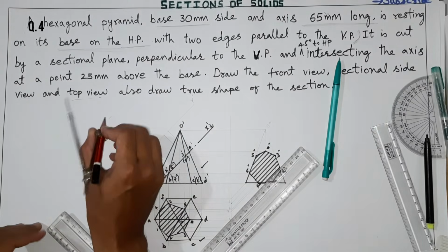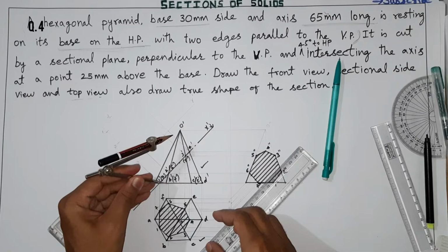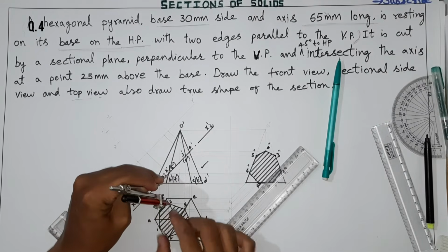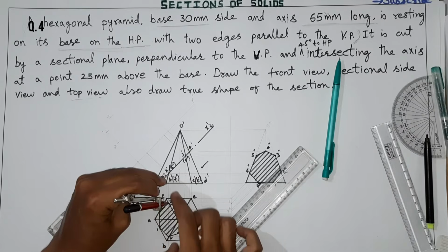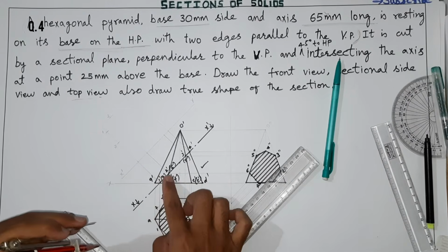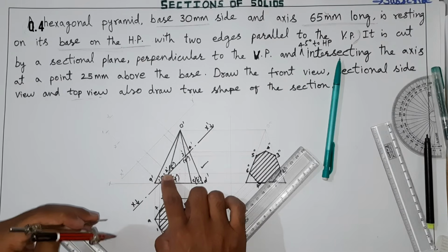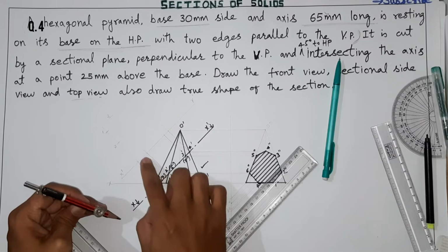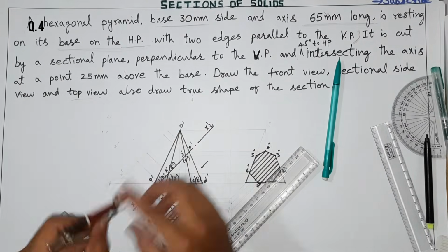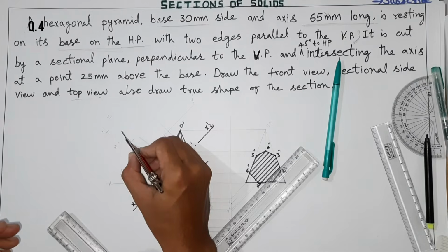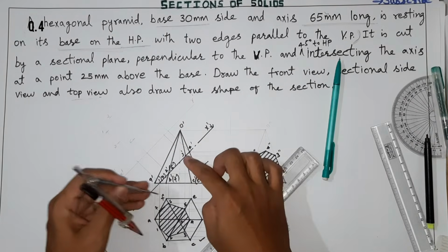So this is your point number 2, and then the same you do for point number 6, measuring from here, old xy line, to point 6 vertically downward distance, and the same thing from this point to this point common for 2 and 6, 2 dash and 6 dash. This continues here, we will mark this one here. So this is your point number 6. Like that continue all other points.